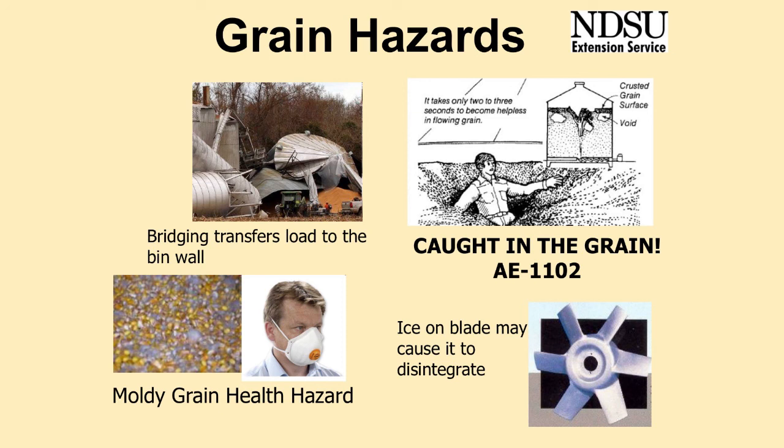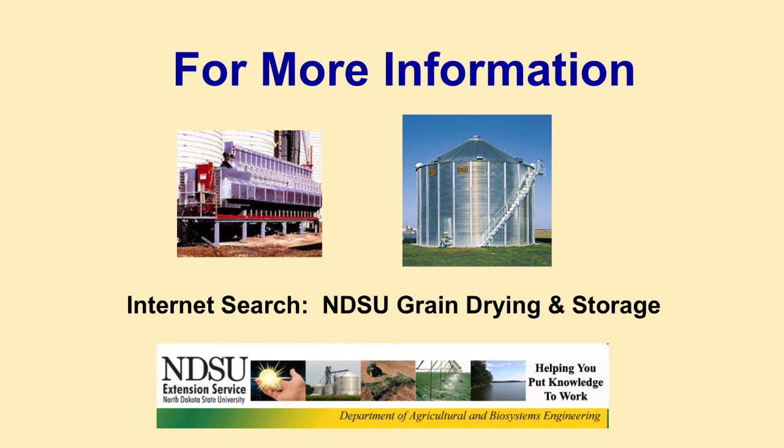Ice accumulation on fans leads to imbalance and vibration. Monitor fans for ice accumulation and remove the ice if it is observed. More information is available online. Do a search for NDSU Grain Drying and Storage.